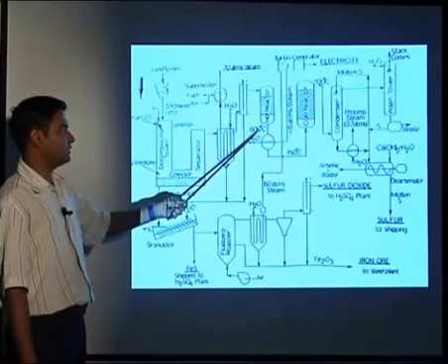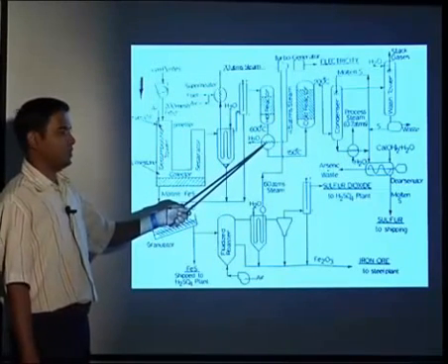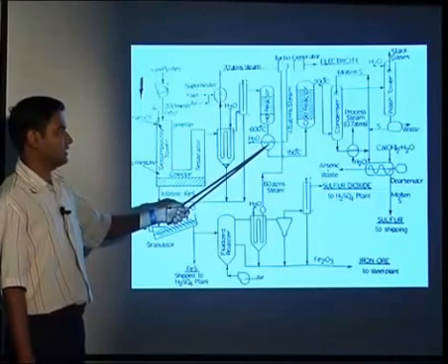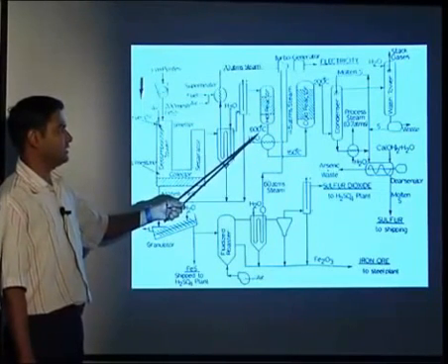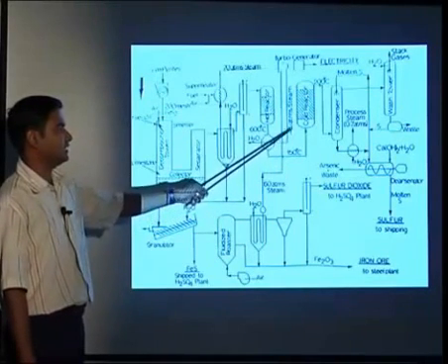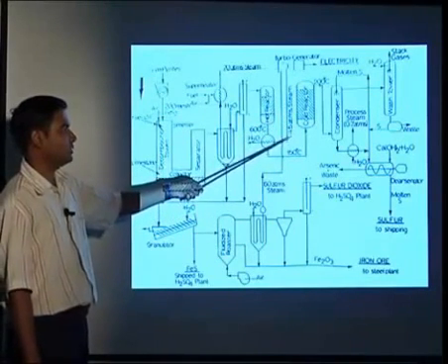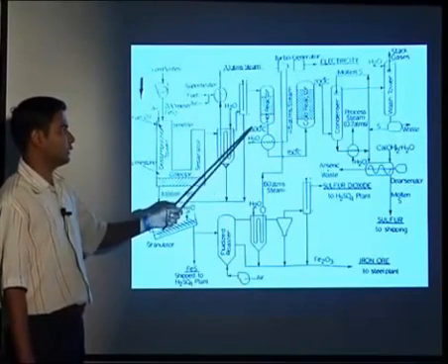The temperature will go up to 600 degrees Celsius, and then with the help of water as a coolant in a heat exchanger, we bring the temperature from 600 degrees Celsius to 150 degrees Celsius, and here also we can get steam of 4.5 atmosphere that we can send to the turbo generator to form electricity.